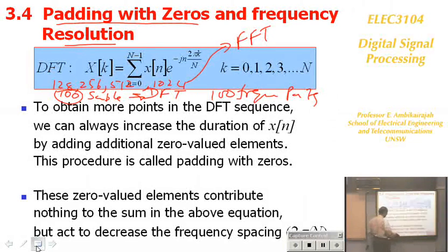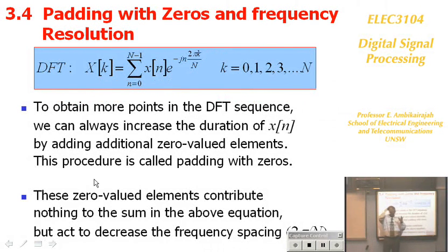But what happens in real time, in real signals? Say you sample the real signal coming out, and you found you got 1,000 samples, but you're short of 24 because the signal only comes for a short time. You sample them fast, and that's it. You got 1,000 samples. You don't have another 24. So if you go for DFT, it takes a long time to process.